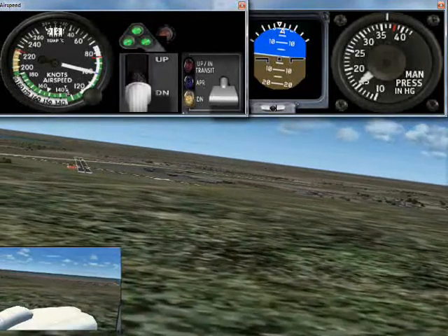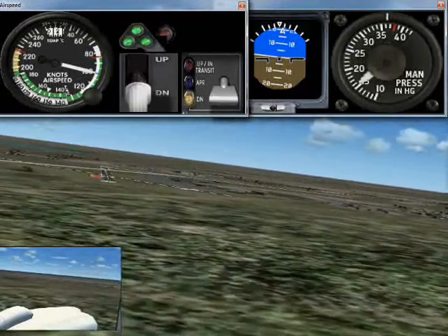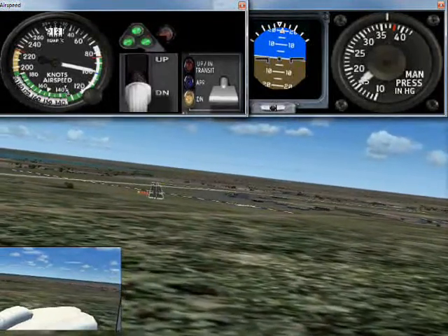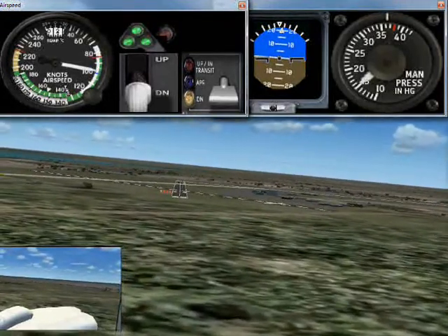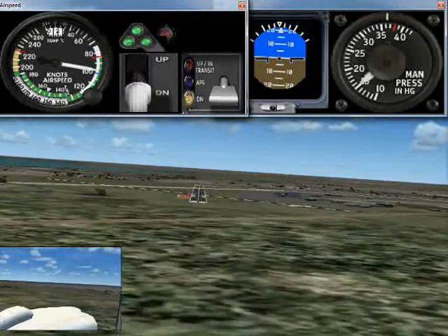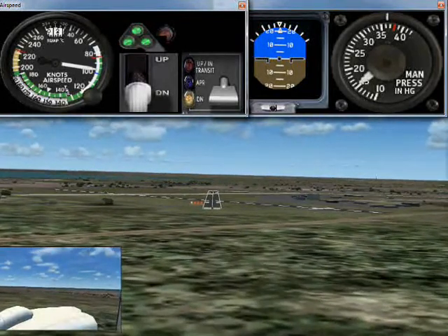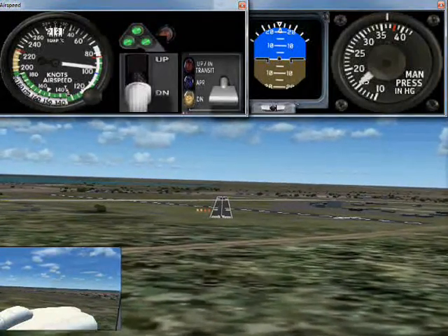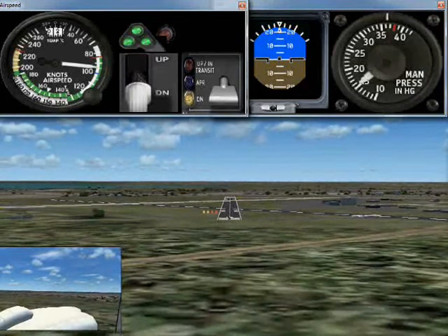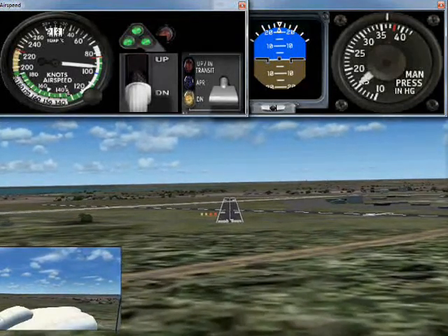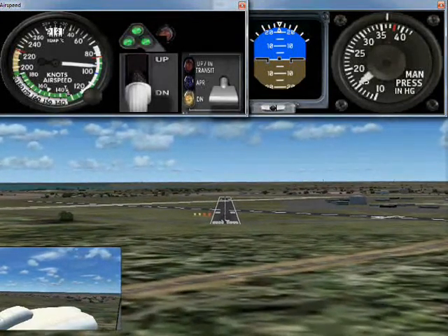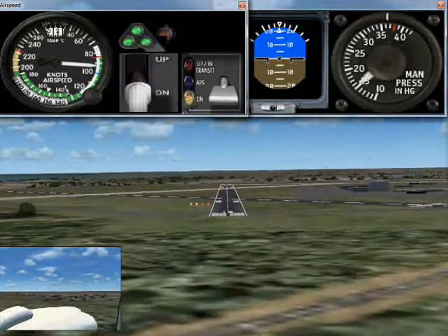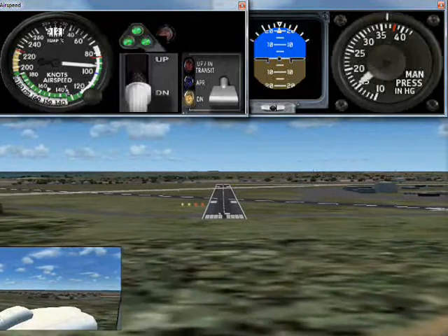Now, as we turn onto final approach, we begin to sense precise visual flight path information, and now have the ability to correct both flight path and airspeed precisely, which is a power variable situation. Therefore, for the remainder of the final approach, we will control flight path with pitch attitude and airspeed with power. We are now aiming for the threshold crossing height with pitch, while coordinating power adjustments to maintain the airspeed constant.